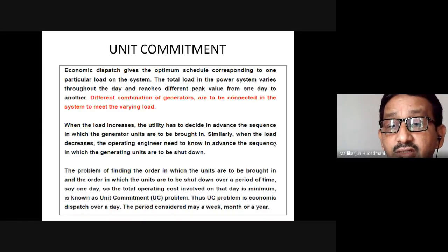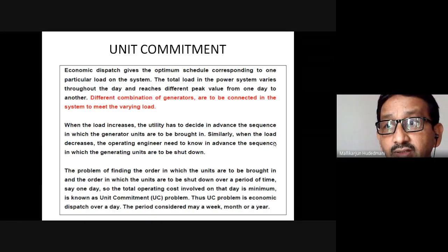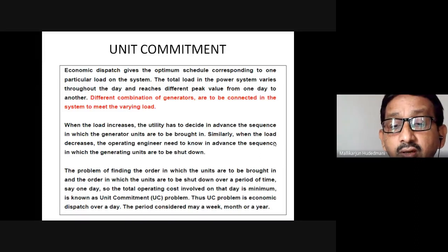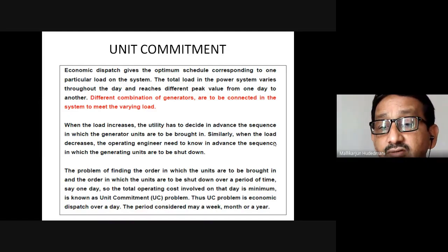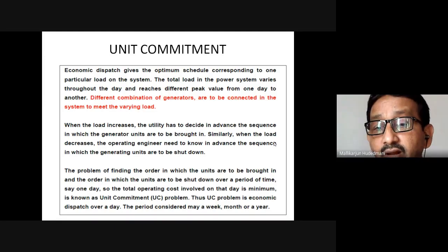Among the available generators in a plant, depending upon the schedule put on that station, how many generators, and which of them, have to share a certain megawatt as a schedule is a decision based on the availability of resource, cost of production and demand. On that basis, certain generators are chosen to meet a certain demand of the station for a certain hour.